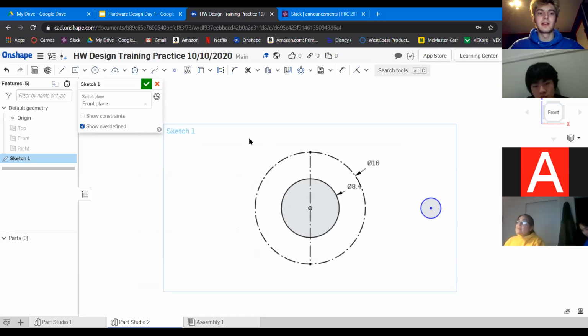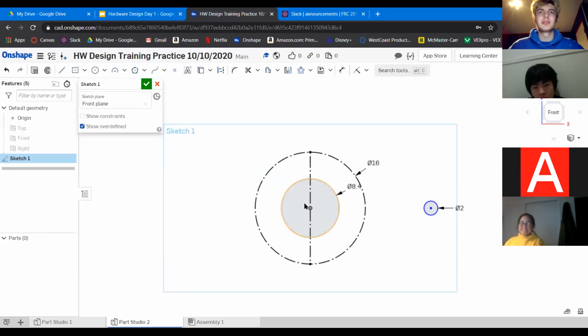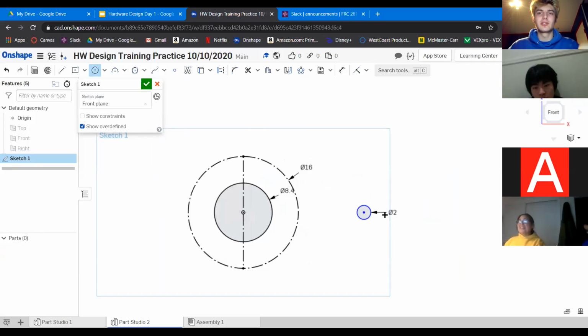right? And I think it was 2 millimeters that I read. See, this little 0 with a slash through it, I think is the diameter notation. I'm pretty sure. So this 2 times 2 diameter refers to this circle and this circle. I'm pretty sure, yeah. So then we're going to want to draw a construction circle around it for the curve around the circle.